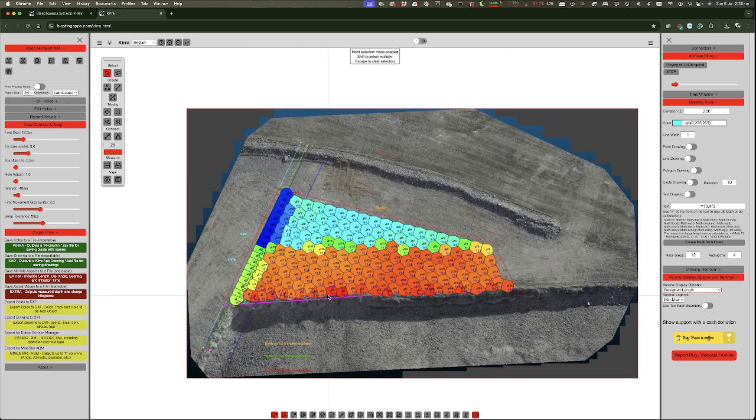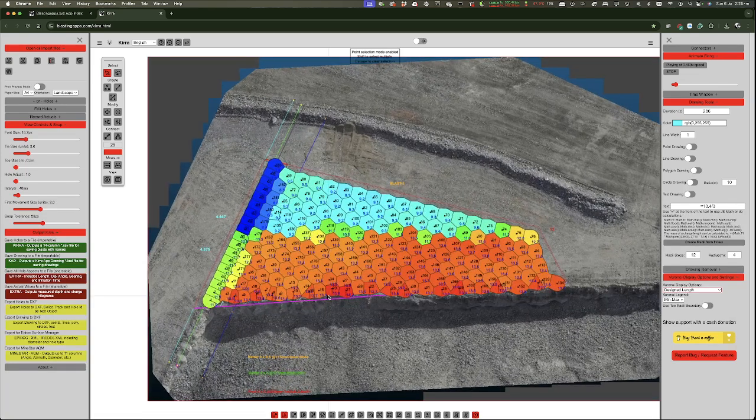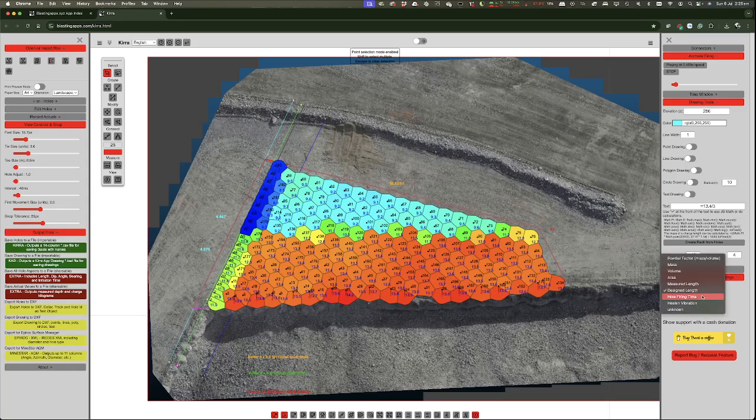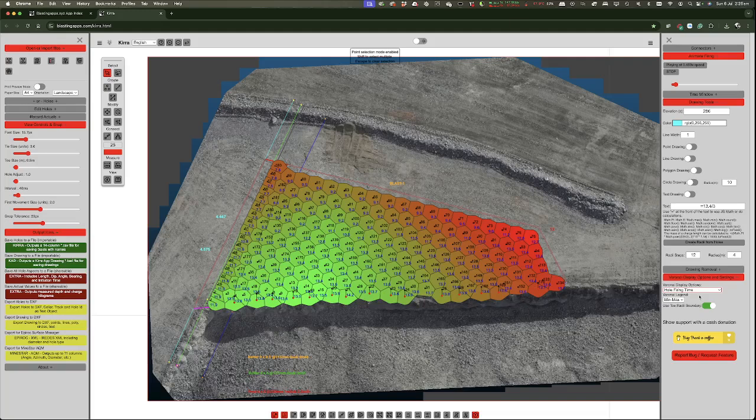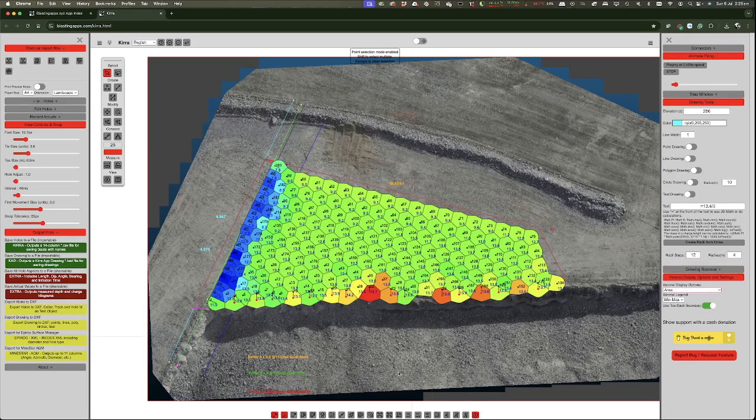Here we can see them calculating the volume there, but we can bring it out so that it's now looking at the toe point, showing you that toe point position. We've got the firing times, so these are our last holes, these are our first holes. I've yet to work on a few of these things down here. I've just been doing what I can do, but area is not bad, so it shows you the area and coverage.